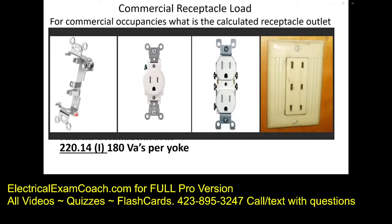What this code is stating is that whether we have a single, a duplex, or even this old school triplex here, each one of those would count as 180 VAs each. I like to think about it as each gang counting as 180 VAs. So if I have a single gang box, it's 180 VAs. If I have a two gang box and they're both containing receptacles on each side, it would count as 180 VAs per gang, and so on as you went to 3 and 4 gangs. Anytime you're dealing with a device strap, whether it has 1, 2, or 3 receptacles on it, it's 180 VAs per yoke.